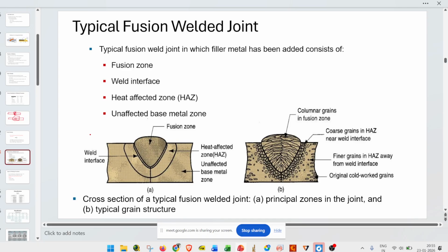They made the Titanic ship so that even if it hit an iceberg, it was not supposed to fail. They designed it at room temperature conditions, but when the Titanic hit the iceberg, it was at a very low temperature. At that temperature, because of the metallurgical properties of that iron, instead of a ductile material it made a transition to a brittle material. That's why it cracked and the Titanic incident occurred.